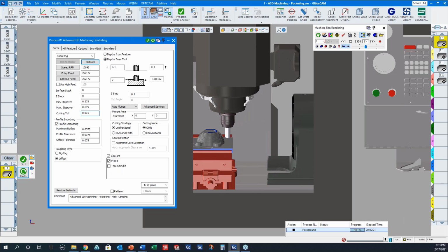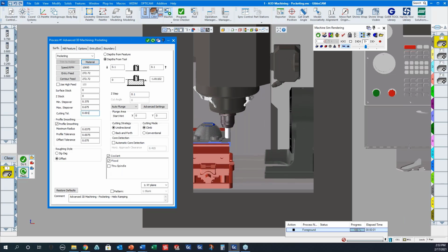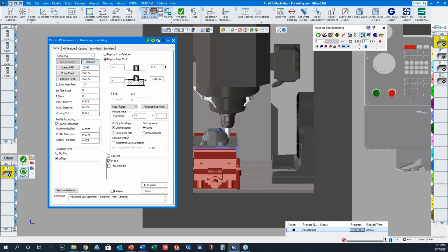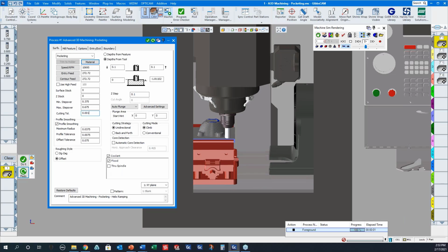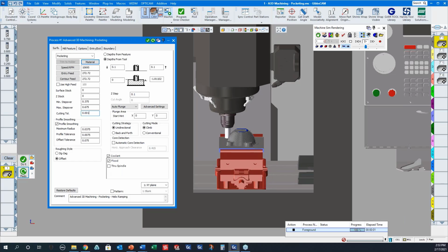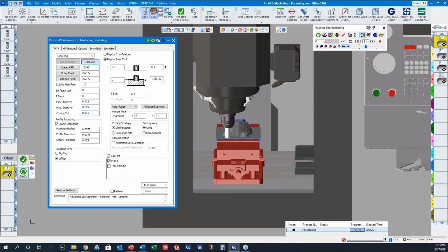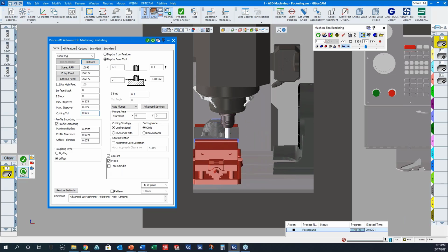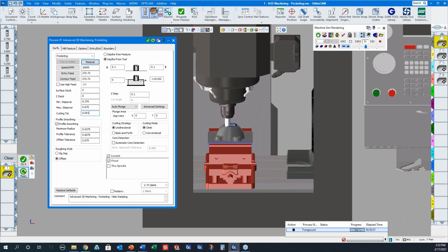Let's see, next question. If you have GibbsCAM 2.5D solids milling, can you program any 3D surfaces with just the 2.5D solids? You can't create actual 3D toolpaths that move up and down in Z unless you've got the SolidSurfacer Advanced 3D machining option.